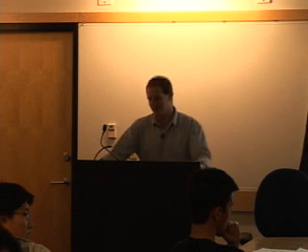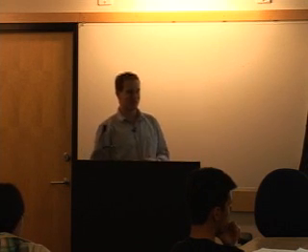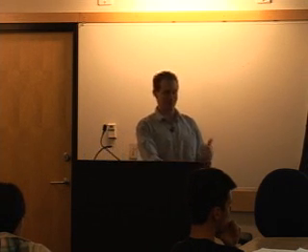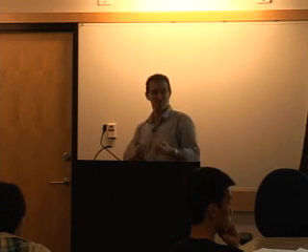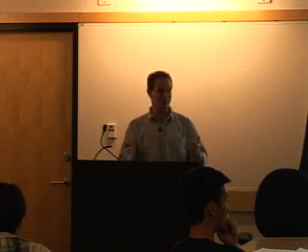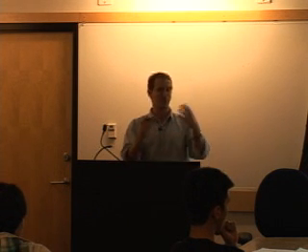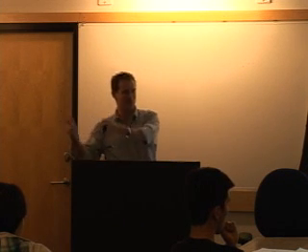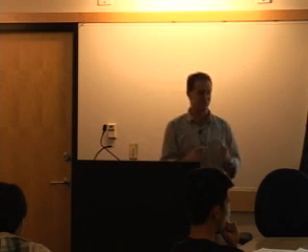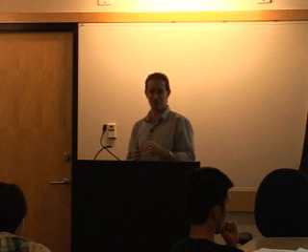Okay. So the question was, when we start talking about input referred noise, there's something a little bit annoying in that, at least for spot noise, it's easy because there's a certain transfer function back and forth. You could always just do the same division. But if you started talking about, for example, input referring the total integrated noise, things indeed get a little bit funky, right? Because you're saying, well, wait a minute, I'm going through some net integrated transfer function, and then when I input refer it, I usually just divide by the in-band gain, or the DC gain, to be more precise. So this is actually a very good question. It's a very common point of confusion.